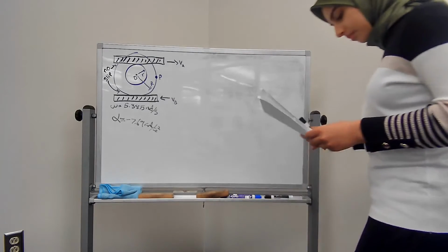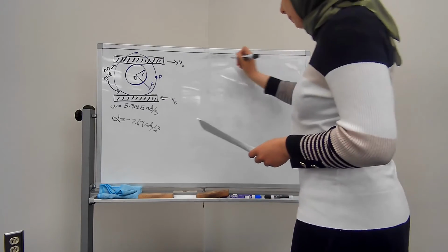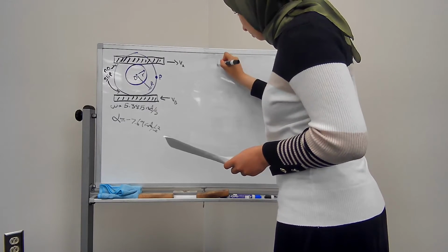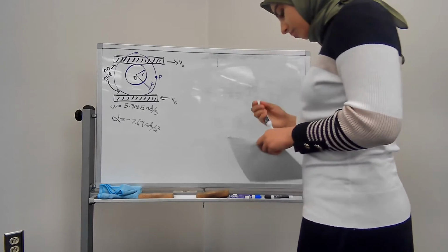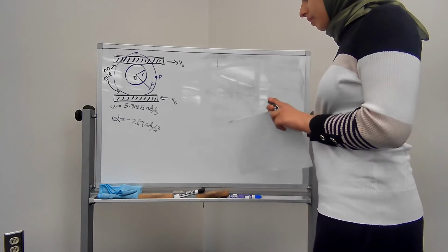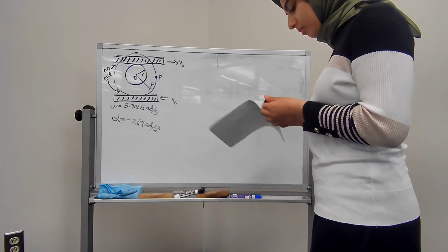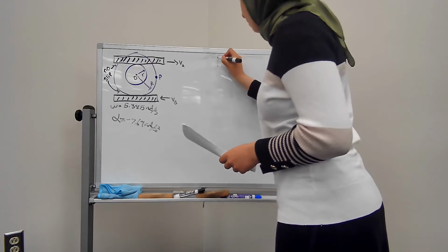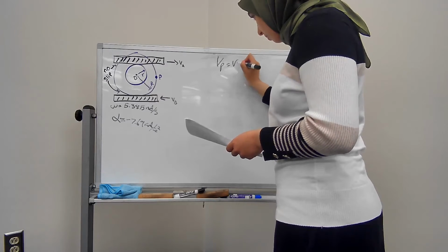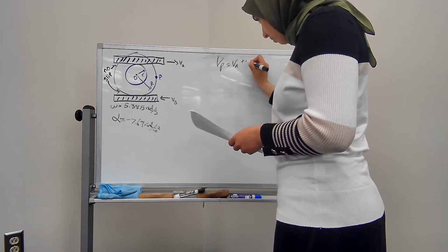Now that the majority of the initial setup is out of the way, we can actually start solving for the velocity at point P. And in doing so, we can use the equation that we've got from this chapter for velocity. That equation for this point in the problem would be the velocity at P equals the velocity at A plus omega cross the R of P slash A.